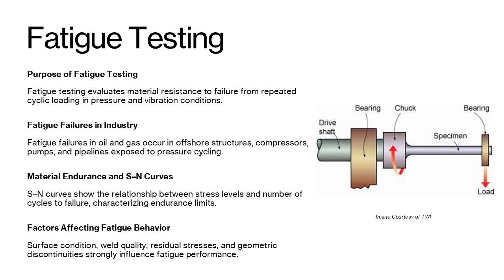Welded joints are particularly vulnerable due to inherent weld toe stress concentrations. Inspectors should correlate fatigue test data with weld quality, ensuring proper profile, smooth transitions, and absence of defects. Understanding fatigue testing enables inspectors to anticipate potential risks and enforce requirements that reduce the likelihood of cyclic-induced failures.